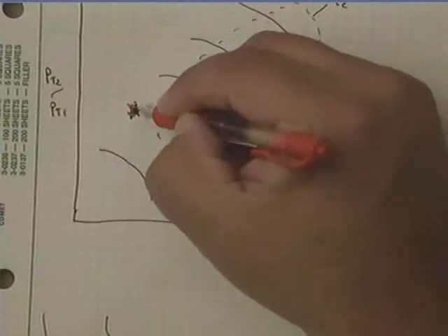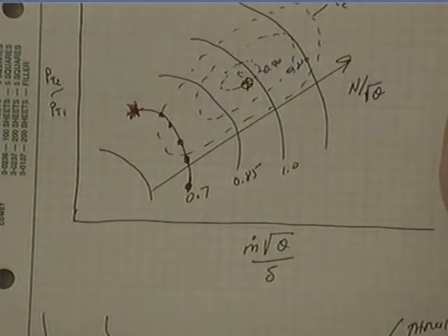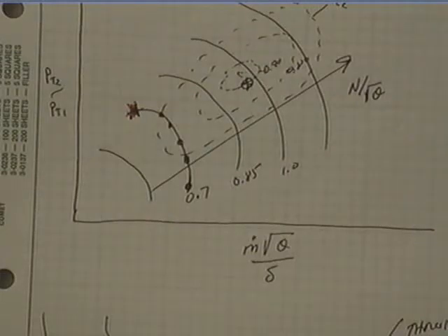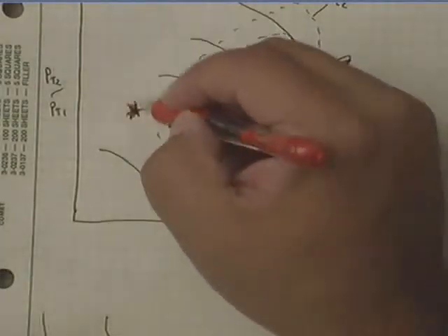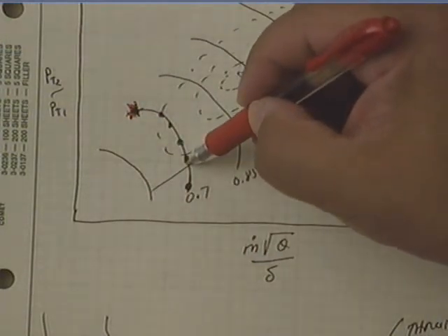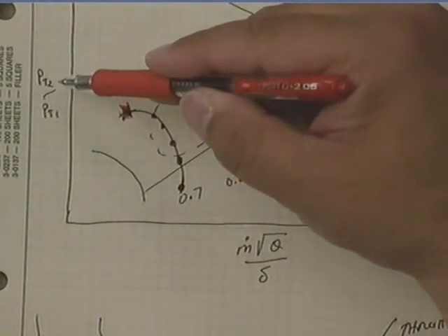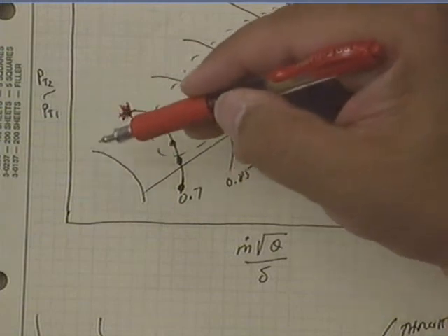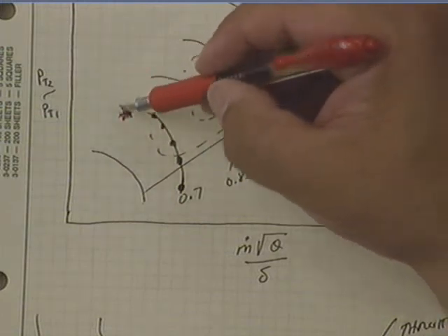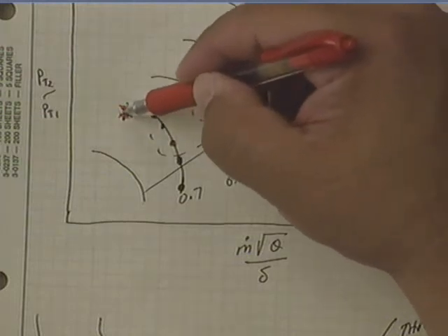So you mark it. This is a very important point, okay? It's sort of like if you take an axial fan that you have in your computer, right, and you put your hand behind it. At some point, you'll stall the flow through that fan, and that is the point you mark down. Now, as you keep throttling the flow, you're getting a pressure rise, okay? So you're loading up the airfoils more and more, and so you get more and more pressure rise. That's a good thing, obviously, but if you do too much, it stalls.